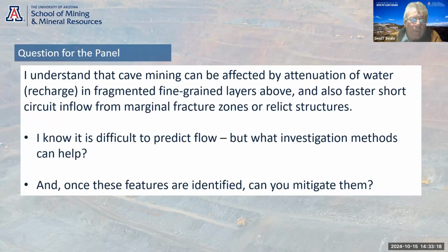If you tie that back into the structural model, you can start to build up a picture of which structures may be important and which ones are not, and whether it's even structurally controlled at all. So as Blair says, focus on the surface monitoring at the top. Monitoring of the draw points is really good. Not that many operations do it well, but many do. Free water, moisture content, and fines content of all the draw points enables you to build up a picture, but it's very difficult to make precise predictions.